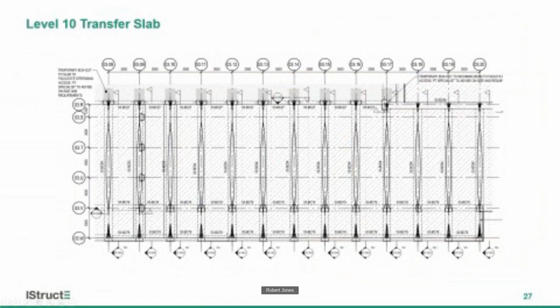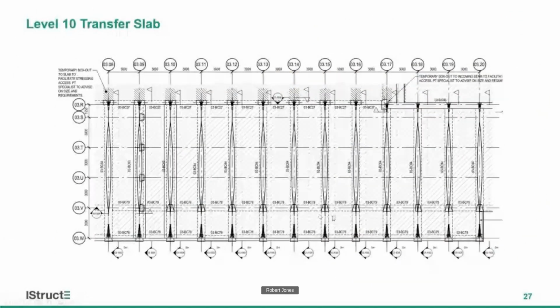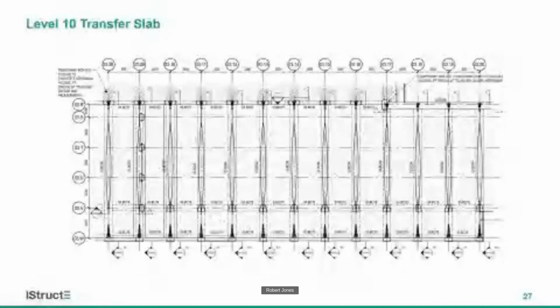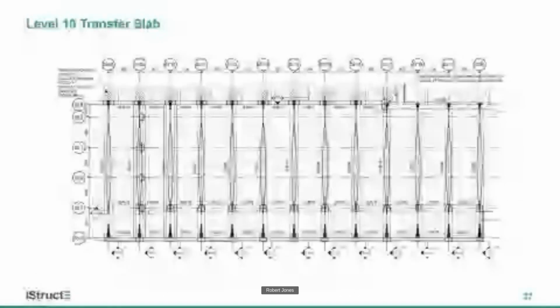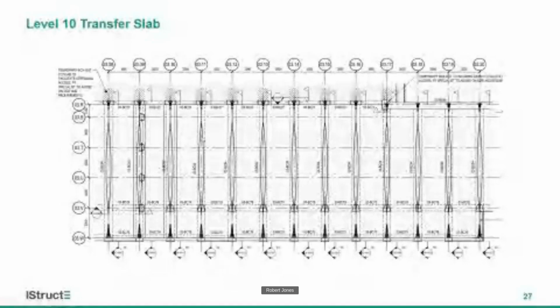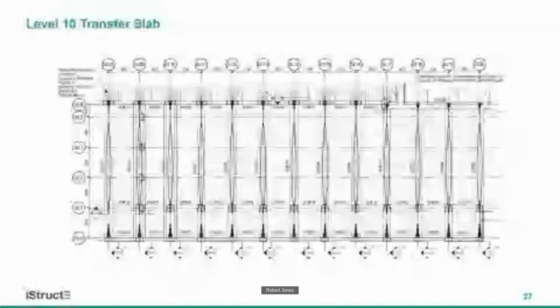And I believe I saw Andy Truby posting a question on the chat. We worked with Andy Truby to look at the feasibility of doing a post-tensioned scheme for this. And in order to get the weight of these elements down, all of this had to be precast to stay with the kind of visual and approach of the building, in order to get the weights of the precast beams down to the tower crane limit that we had set from Mace, which was 10 ton.